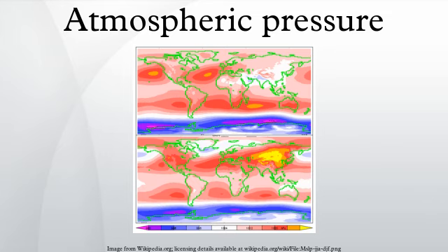Atmospheric pressure based on depth of water. Atmospheric pressure is often measured with a mercury barometer, and a height of 760 mm of mercury is often used to illustrate atmospheric pressure. However, since mercury is not a familiar substance to most people, water may provide a more intuitive way to visualize the pressure of one atmosphere. One atmosphere is the pressure caused by the weight of a column of fresh water of approximately 10.3 m. Thus, a diver 10.3 m underwater experiences a pressure of about 2 atmospheres. This is the maximum height to which a column of water can be drawn up by suction at atmospheric pressure.